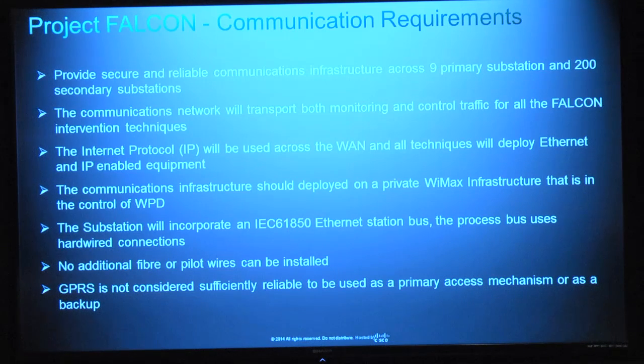The substation technology for each of the primary and secondary substations was to be derived based on IEC 61850 as part of the trial, and a constraint that was applied was that no fibre or pilot or copper wires were to be installed anywhere. There is a complete restriction on that in the United Kingdom, which personally I found to be quite challenging when we first showed up, because virtually every utility has lots of wires to every substation they have, but this was the first time I came across a utility or a market where the wires don't exist. You actually needed to use radio technologies.